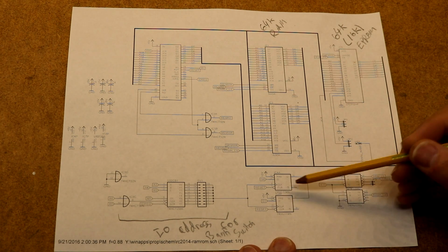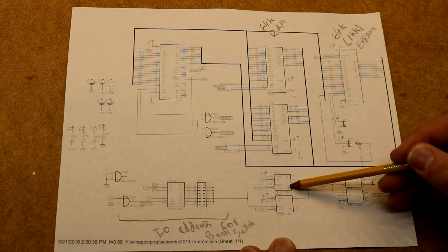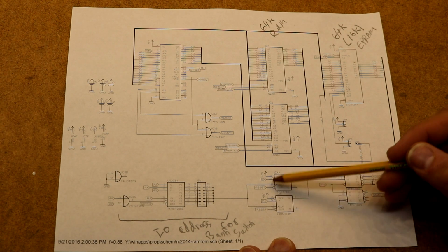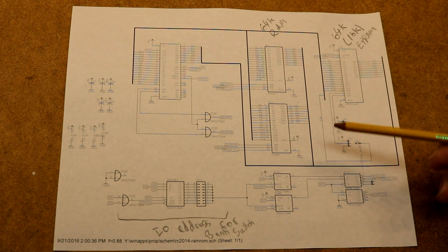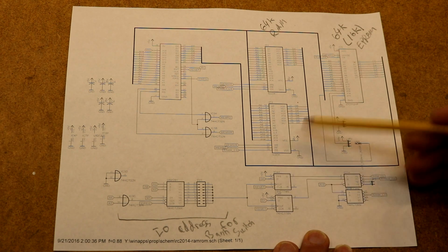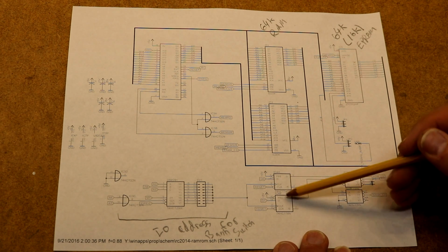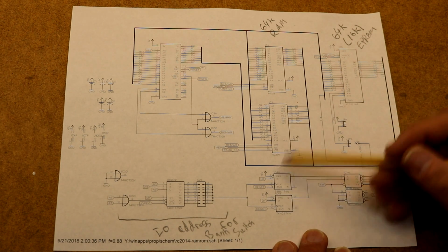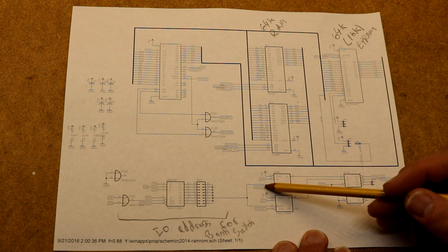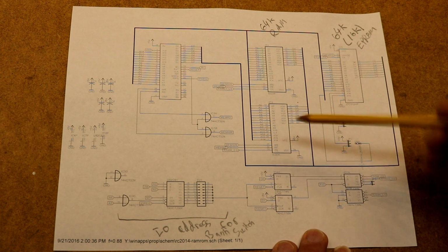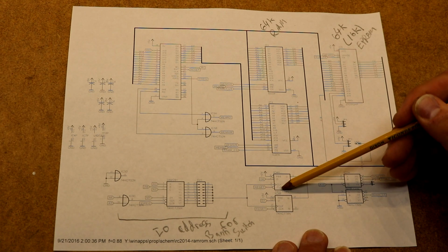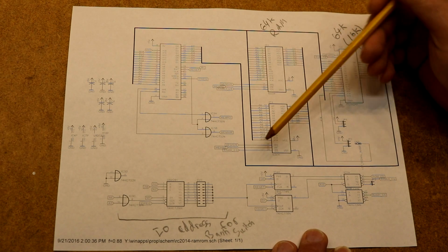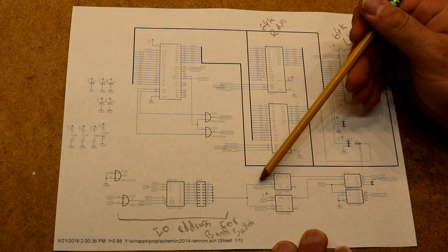Now there's a couple of flip-flops here that I use to store the current state of the bank switch. And that'll store 2 data bits. That allows us to select any of 4 banks. So the way flip-flops work, of course, is you can clock it, and it will clock that data into the flip-flop. And the handy thing about a flip-flop, at least this type, is it also has this reset clear bit. And if you put this clear bit low, then it'll reset the flip-flop to zeros. And we're going to use that to handle our power on situation.